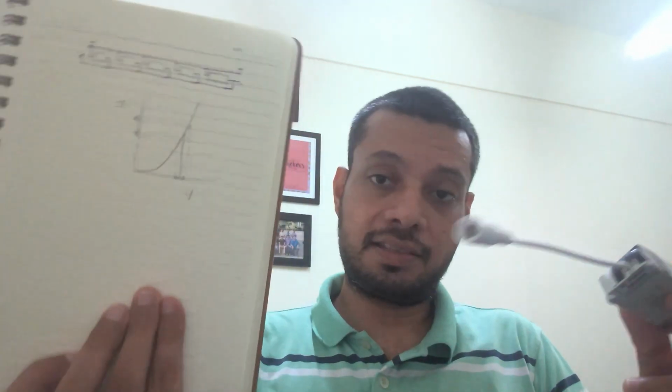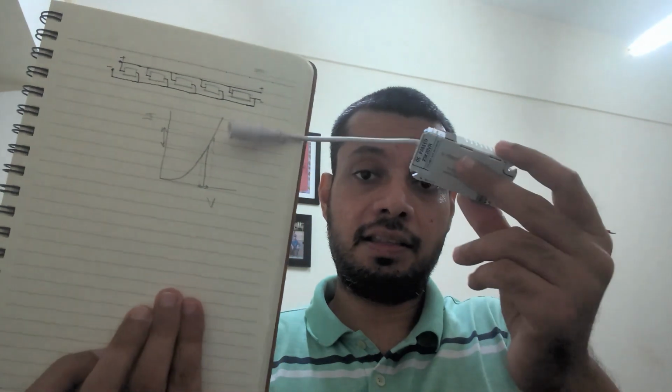If you see, it also clearly mentions on the top, it's a constant current LED driver, right? That implies, that is what we were talking about, that this forces a constant output current, and the voltage gets automatically decided by this output current and the LED characteristics, right? Based on the current and the characteristics, the voltage gets determined.